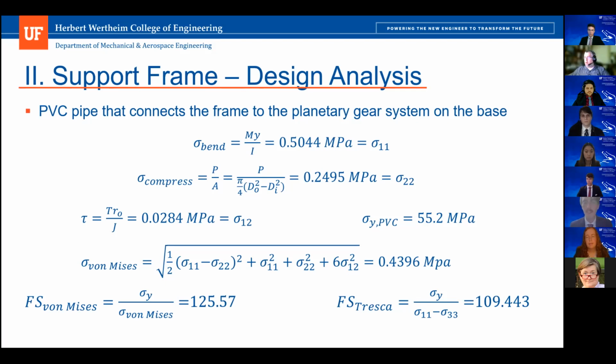The weight of the frame, motors, and reflectors supported by the pipe is equal to 183.37 newtons, causing compressive stress of 0.2495 megapascals.